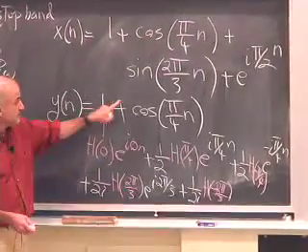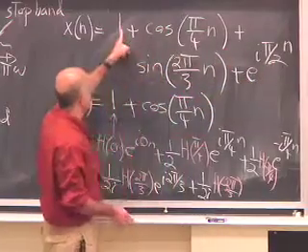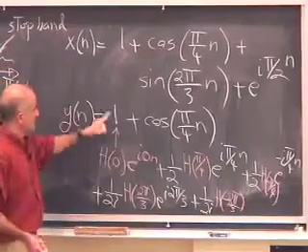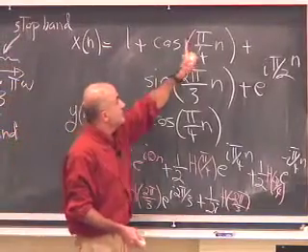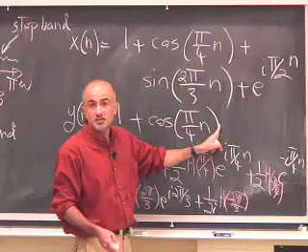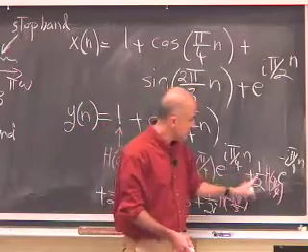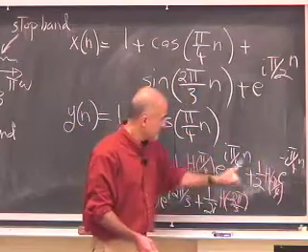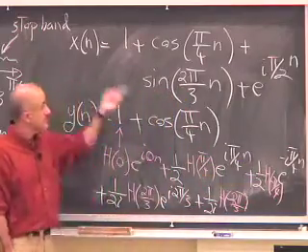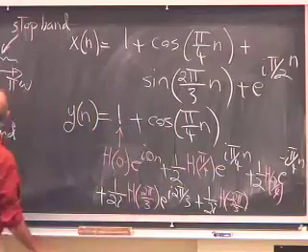If you're fluent, you're going to write this right away, and you're going to say, this frequency gets killed. This is 0 frequency. The DC gain of the filter is h of 0, which is 1. So 1 comes out, unchanged. Pi over 4 minus pi over 4 is in this part. Each gets amplified by the same number. So if you start off with 1/2 this frequency plus 1/2 negative the frequency, because the amplification on both is the same, you can factor that out. In this case, it happens to be 1. So the same cosine comes out scaled by 1.